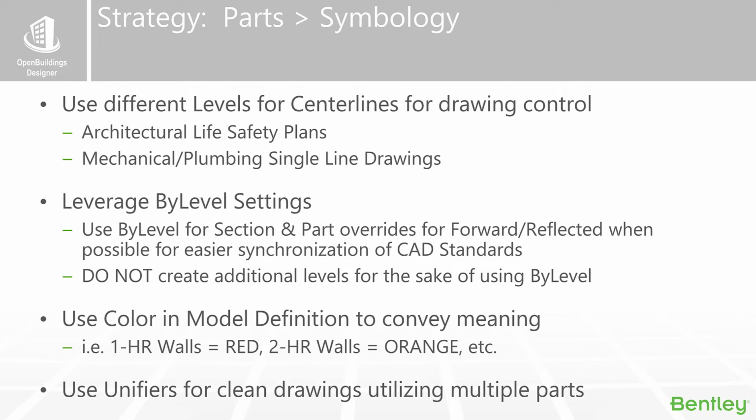And then, as we were looking at center lines, you could have different levels for drawing control, for life safety plan, mechanical, plumbing. You can be using ByLevel, but we don't want people necessarily creating additional levels to be using ByLevel. People using ByLevel is more for going output to DWG. But in your model you can be using the colors of what objects are. So if you have CMU walls, 1 hour, 2 hours, they could have these in different colors so you can immediately see what the ratings are, or you could be using display rules as well.